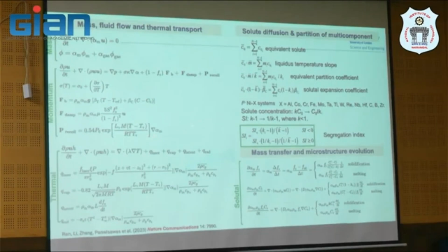This is actually a multi-phase solver. And then in the thermal part, we can add thermal terms like the laser profile, whatever fancy term you want to add. For example, there is some research talking about changing the beam profile, which only limited manufacturers can do, right? The beam profile changing, like ring donut or ellipsoid or Gaussian, and so on. That contributes to microstructure development. This can be done in principle. Anyway, welcome for collaboration on any of them.